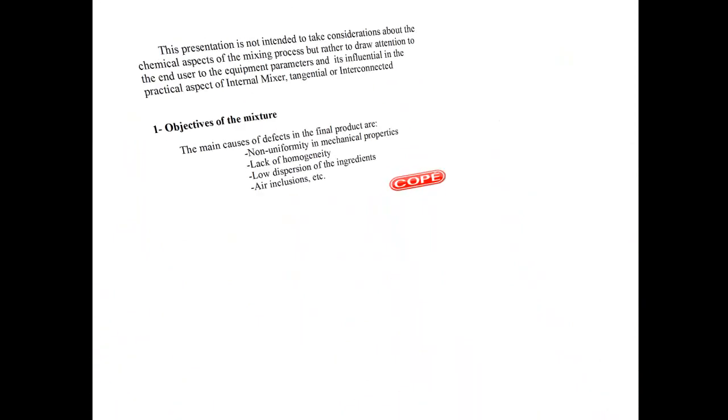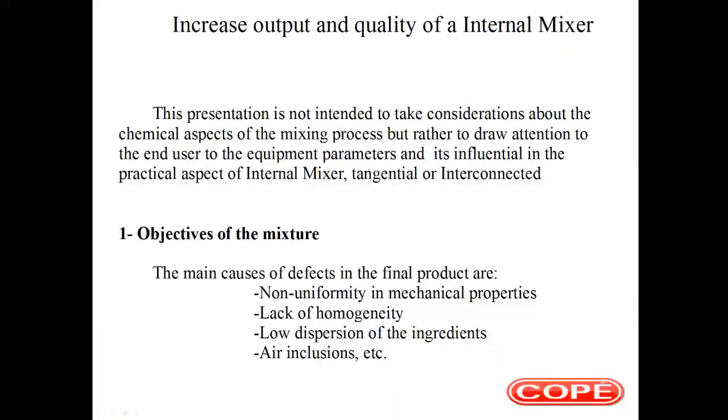When we talk about the final mixers, we have to pay attention to the main causes of defects in the final products, and they are non-uniformity in mechanical properties, lack of homogeneity, low dispersion of ingredients, and air inclusion. These are the most important factors for uniformity.